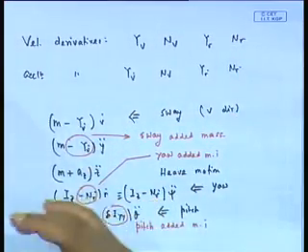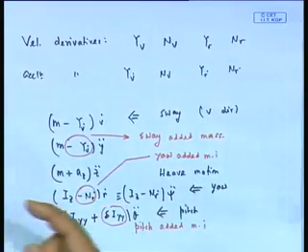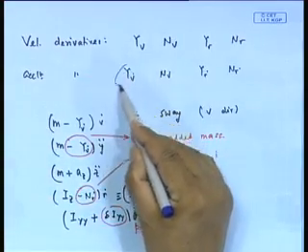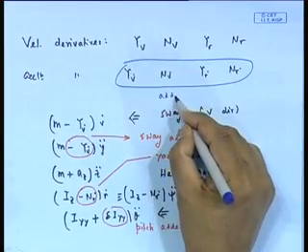Again, added mass, added moment of inertia are also intrinsic property of the hull. So, we now understand this. Now, why I am saying is that these terms, these acceleration derivatives, essentially become what we call added mass forces.